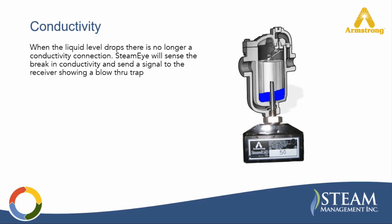If the trap develops a blow-through condition and begins passing live steam, the condensate level inside the inverted bucket trap drops or even disappears at times. Once that liquid level drops below the probe, conductivity is lost. The SteamEye transmitter immediately recognizes that loss of conductivity and communicates the alarm back through the system. This allows maintenance personnel to quickly see when an inverted bucket trap has failed, rather than waiting until the next survey or inspection, as you guys were referencing earlier. The result is faster detection, faster repairs, and reduced energy loss.